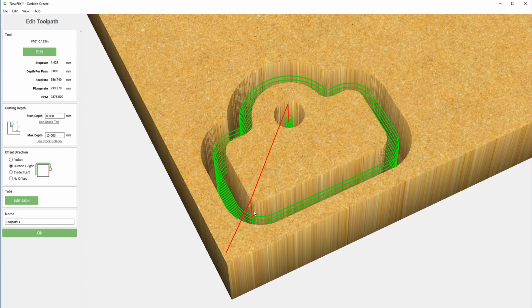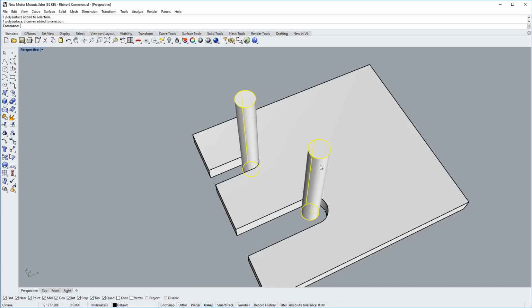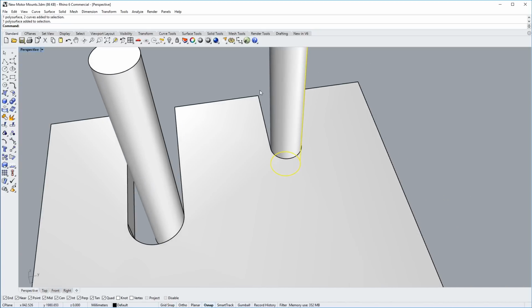And the other functionality that I would love to see for cutting metal especially is something that I'd like to illustrate in Rhino. These 2 cylinders represent 2 of the same bits as they're spinning, and in this instance we're pushing the bit straight through the material, just augering straight through, and 100% of the diameter of that bit is engaged cutting through that material.